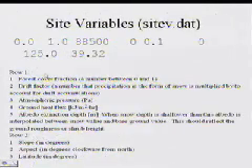Then there are site variables that are specific for the site that you're applying it to. The forest cover fraction, the drift factor, a number that represents how much the precipitation is multiplied by. If you're applying this on a grid over a watershed, that might be different for each grid, as we did for Upper Sheep Creek.